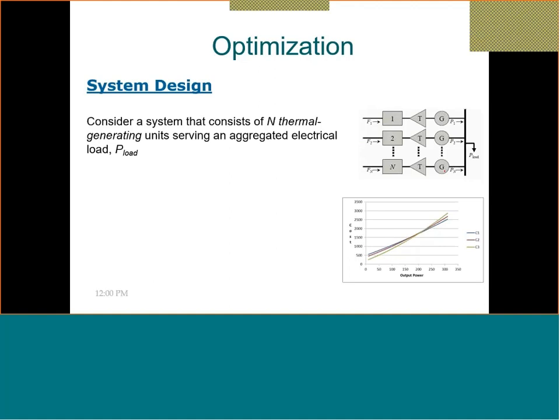For example, there are certain overhead lines. I cannot have more than this amount of current. Why? Because this is what we call the limit. If we try to push more current than the conductor can take, this will lead to big problems. So we do not exceed the thermal limit of the conductor.